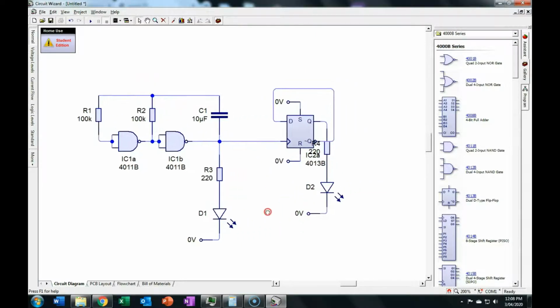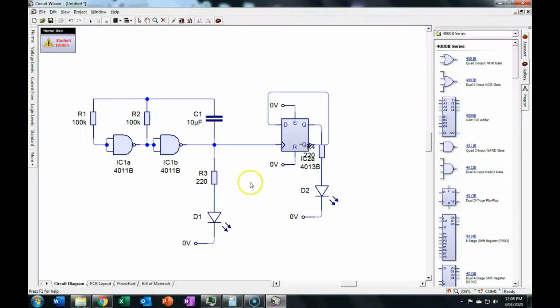And what we should see, just like with the first Prac that we did on flip-flops, is that whenever this gets a rising edge, positive going edge here, we should see the output change, and because it's set to toggle, this is going to cycle between logic high and logic low. Just clearing up some of those things in there. Alright, so now if I run the simulator, you can see that whenever this one turns on, supposedly, this one changes.